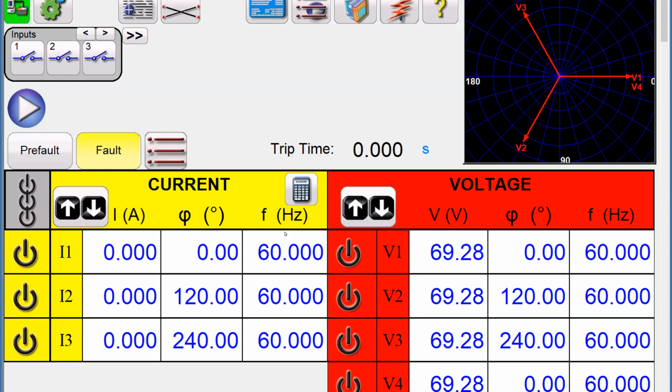So this is RTMS. This is Relay Test Management Software, and this is what we're going to use today to actually perform the test on this 351 relay. And we're going to test the ones that I had the settings for that I showed you in the past 2 slides. So I want to give you a quick look of what we're doing here.